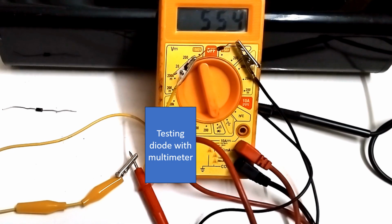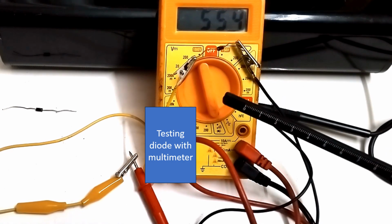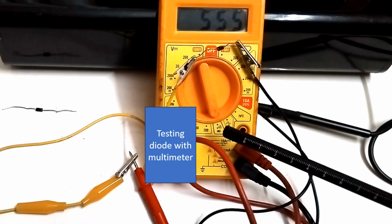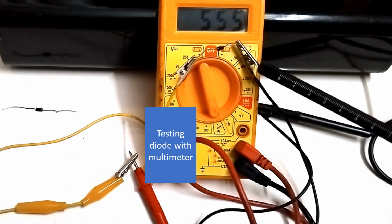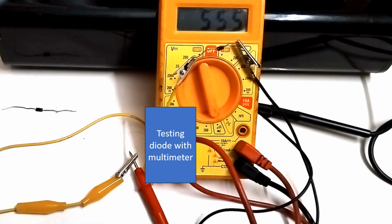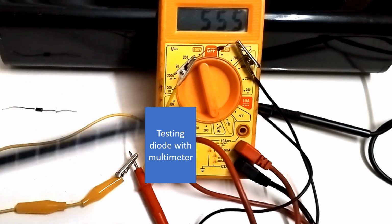For testing a diode, you have to choose the selector switch in such a way that it indicates the diode symbol. That is how you test it. And then the black lead is connected to the cathode and the red lead is connected to the anode.